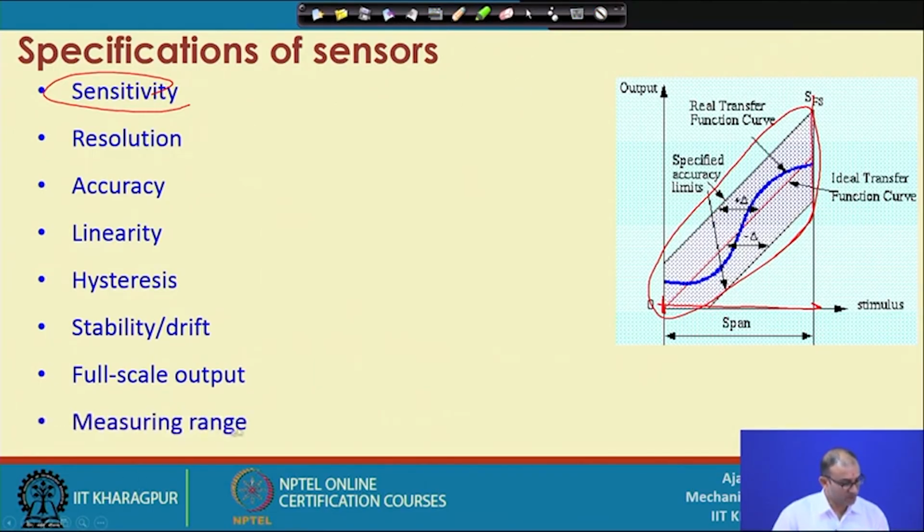Right. What is the measuring range? That is very important here, because we know here in micro machining that most of our forces are very small, right. So, suppose you want to measure some force, starting from 0 and you want to measure only up to 10 Newton, right. Now you consider that all your force measurement comes within the 10 Newton, then you can actually increase the sensitivity to a very high value.